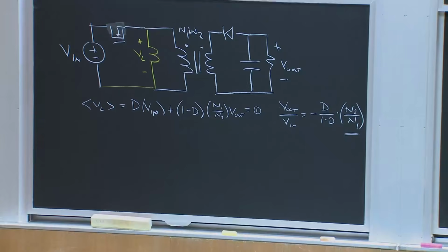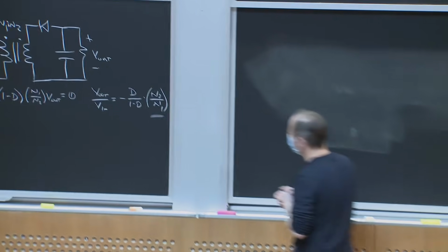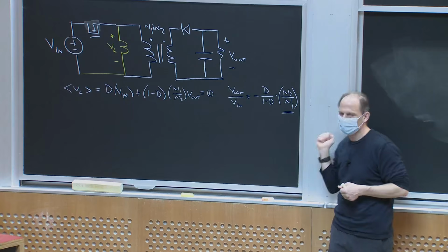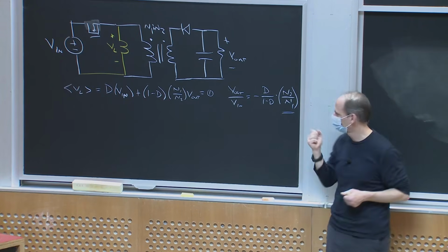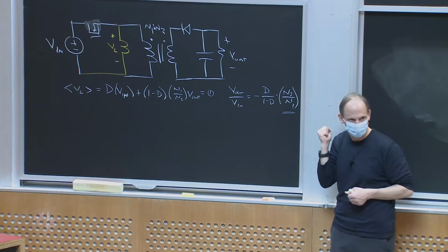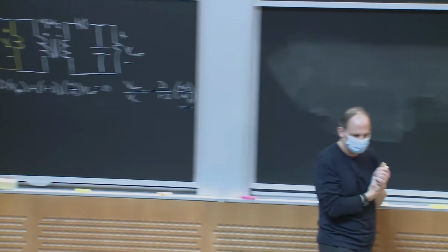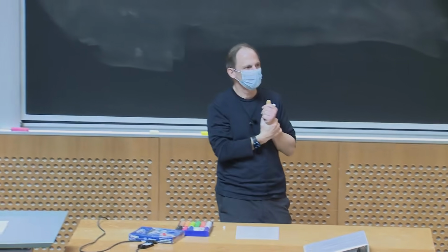And that will let me get a certain voltage conversion ratio. It gives me an extra way I can scale the output voltage compared to the input voltage. A fixed scaling is set by the turns ratio, but nonetheless it lets me pick my duty ratios the way I want. Okay? Any questions about that, rescaling?